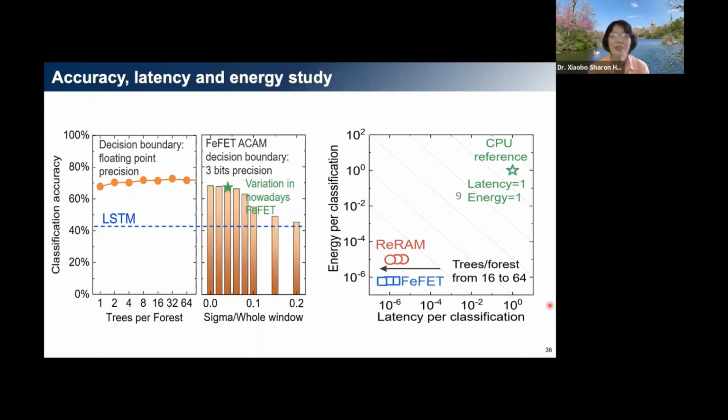When the standard deviation is high, that means we have a big difference between the minimum and maximum. What does it mean in your application in terms of hardware design? So when we say the standard deviation, we actually mean when you set a particular VTH. Let's say you want the threshold voltage to be at 0.5, but then when you write it, you don't get 0.5. You will get, say, 0.45 or 0.65. It could be on either side, right? Now, what it means on the application side